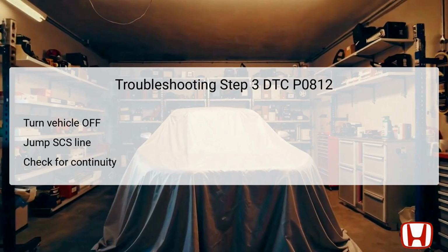Test point 1 is located at PCM connector A51P, number 16, while test point 2 is connected to body ground. If continuity is present, it indicates that the ATPR wire is functioning correctly, and further investigation should focus on any service information related to DTCs. Conversely, if continuity is absent, this indicates a fault in the wiring, necessitating repairs to restore the connection.